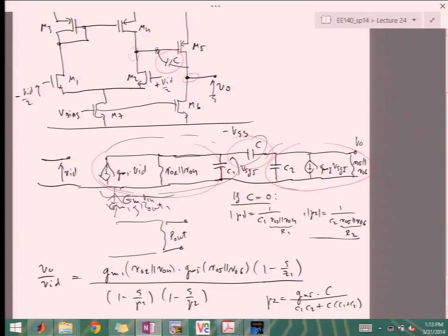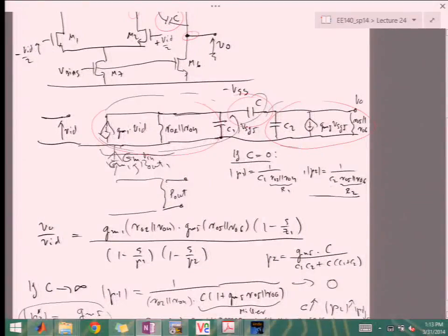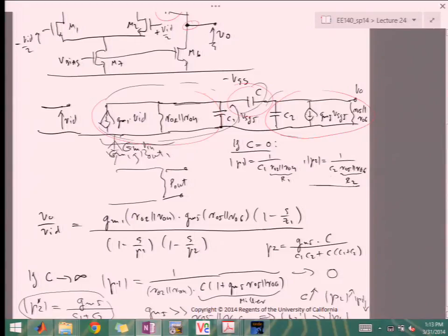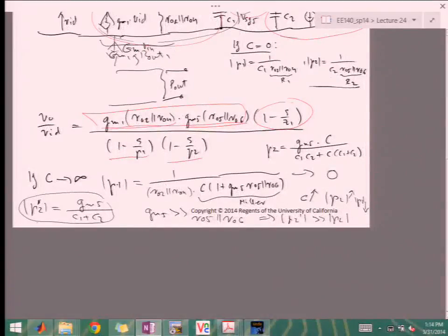We've covered that previously with 2-stage op-amps, as well as in the CGD impact on a single stage. You always get this kind of topology. What we derived was that if you write out the nodal analysis, you not only have these 2 poles and a classical DC gain, which is just stage 1, stage 2 GMs and R outs, but you also have this zero.